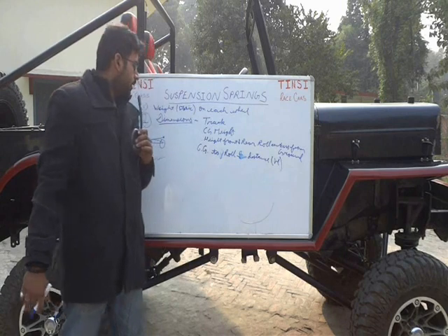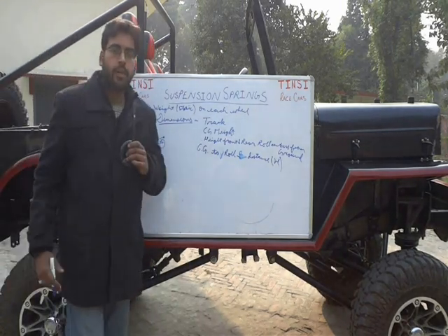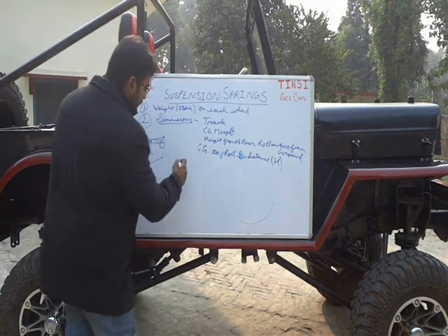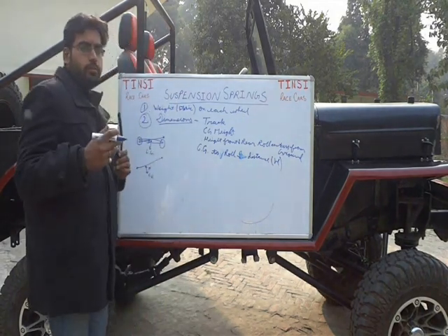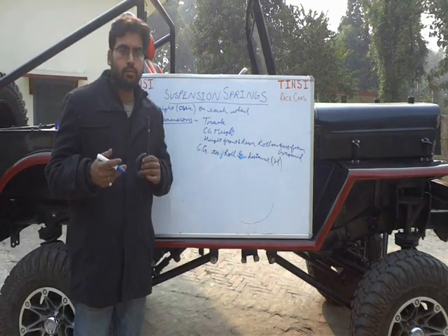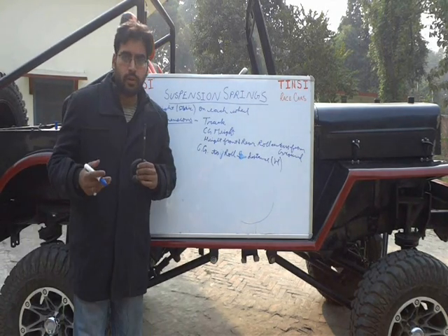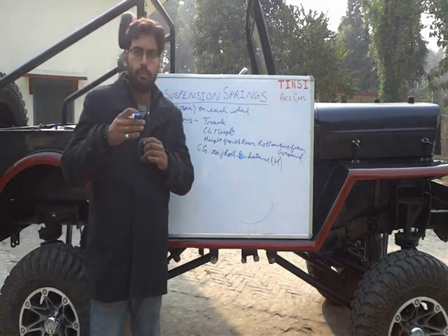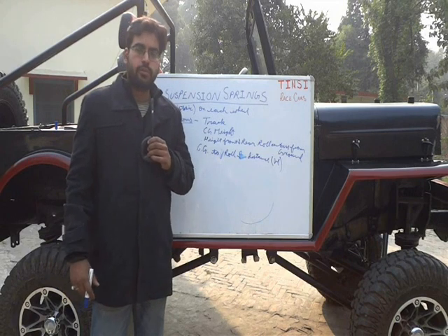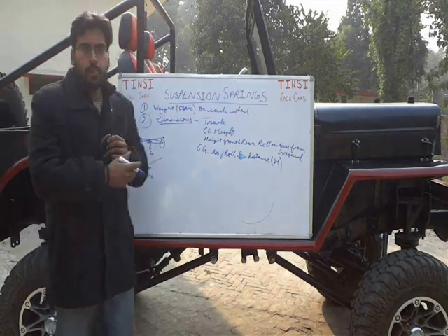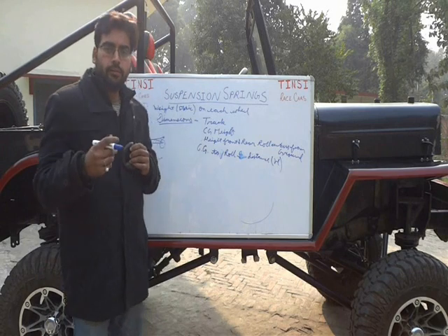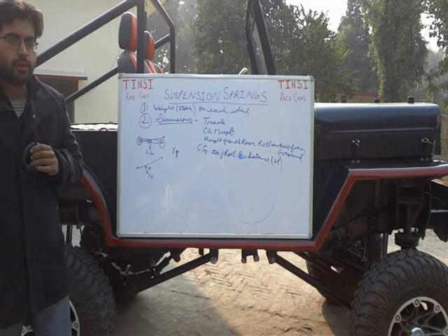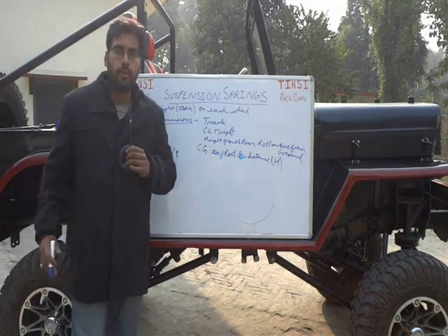So after you're ready with your weight and your dimensions, next we go for the weight transfer. Assume a particular value of G, the lateral force that you are trying to take, in a cornering situation. When you are making a vehicle model, you can do this for a number of G's of cornering forces that you experience. But here I'll just take an example for a single 1 G of cornering. Suppose we are taking load transfer at 1 G, pure lateral.